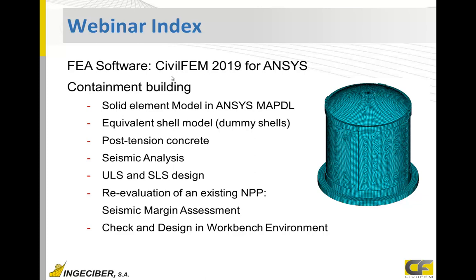So, these tools that we will see in this example, the first tool will be the equivalent cell model. What this tool does is generate an equivalent cell model to the solid element model, and it will be used for checking and design to obtain reinforcement amount, cracking checking, all checking types we can perform. The target of this cell model is that the solid element results are stresses.